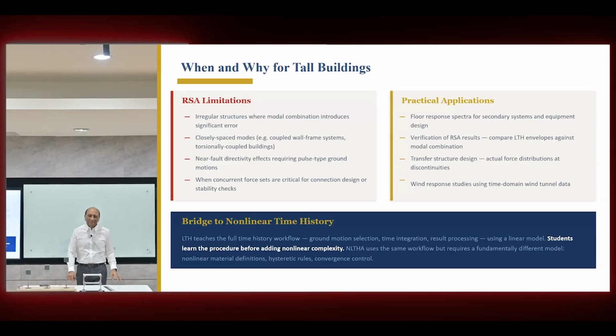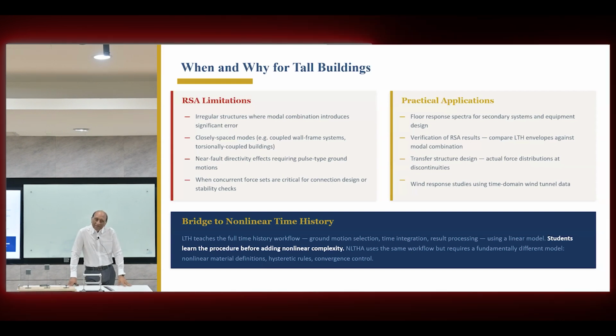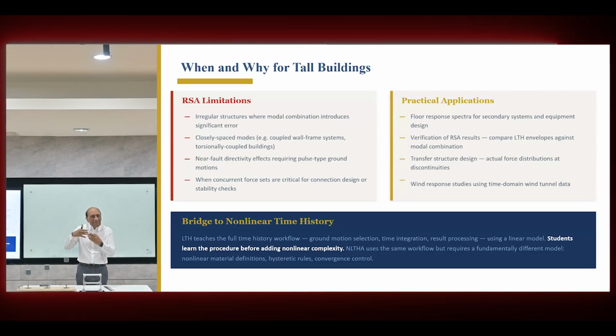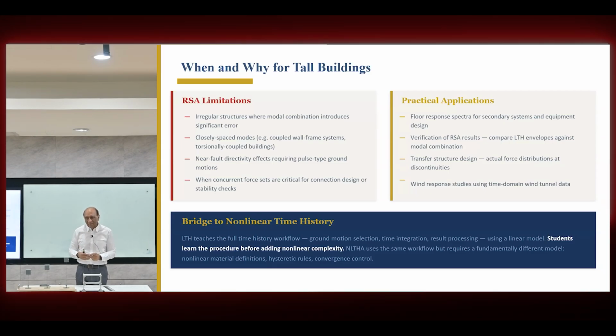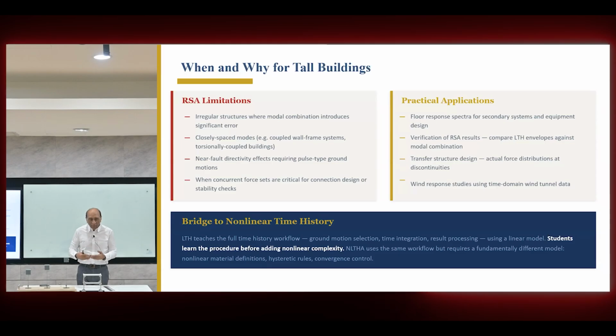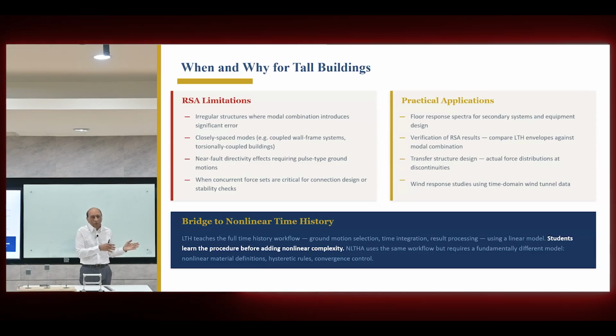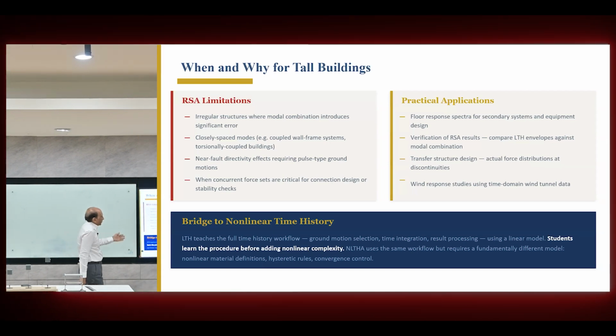When you design connections, for example, then the response spectrum analysis is not really suitable because you are taking the plus minus, but for the connection, the direction of the force matters. Which direction, force, and quantity with which to be combined, it matters. Tension and compression are not the same. So that's why the direction of the force is important to design something, but response spectrum always gives you the absolute value. And you don't know, and you have to use both directions, which is also incorrect. So these are some of the drawbacks.